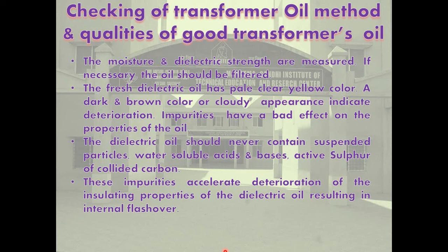Dust and other particles are removed by means of filters in the oil filtering unit. Moisture in oil lowers the dielectric strength, thereby causing internal flashover. Moisture is introduced in the transformer through defective seals. Sometimes oil filled in the transformer may itself have higher moisture content.